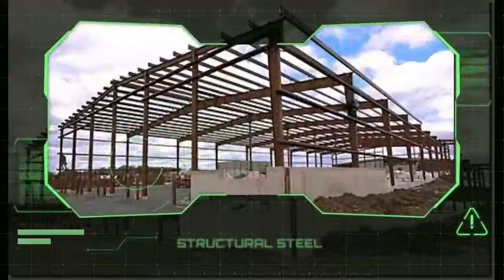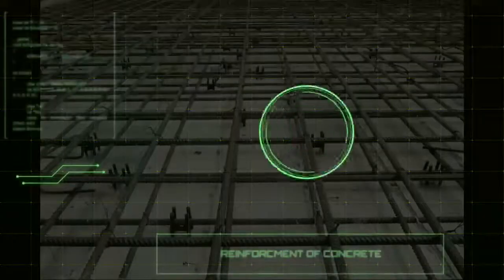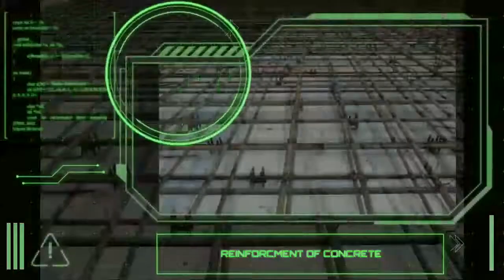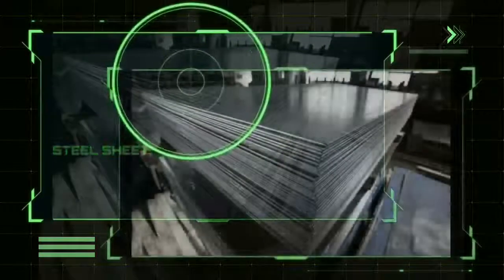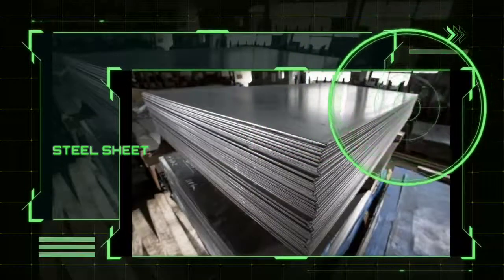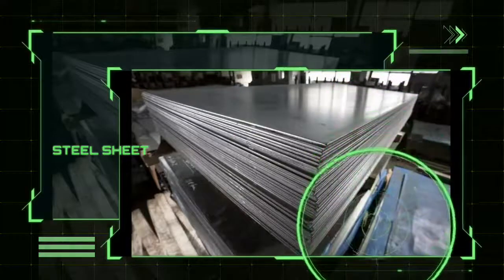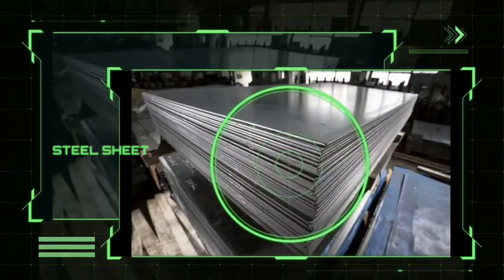Structural steel is a rolled steel that is used in construction or building projects. Reinforcement of concrete, usually deformed bars of varying grades and diameters. Steel sheet. Steel sheet is made from low carbon steels, generally containing about 0.15% carbon and not exceeding 0.25% carbon.